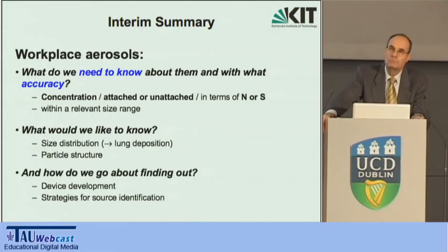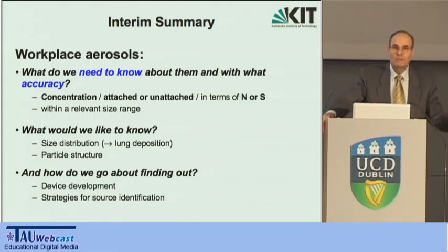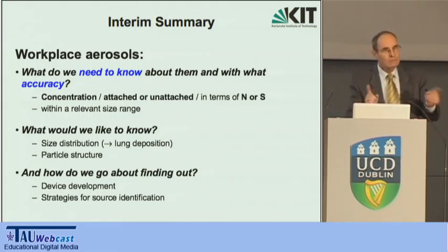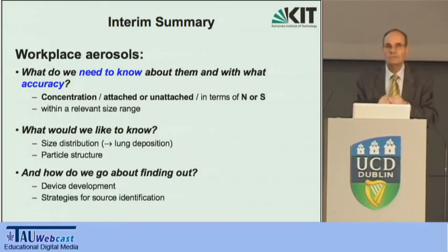Aerosol people have developed all kinds of neat strategies for source identification. Okay? And those are not just plugging in an instrument and taking a reading of a size distribution, but they go about doing differential measurements. They will go into different parts of a facility and check concentrations, and then look at whether there are significant changes in the spectrum.